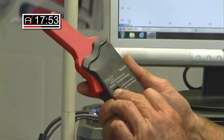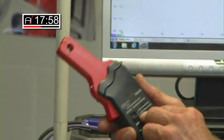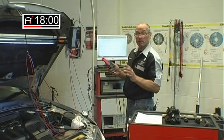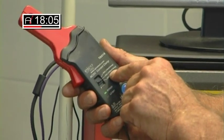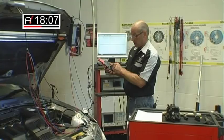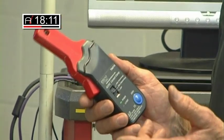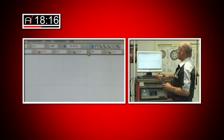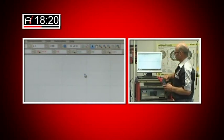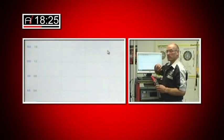We turn the Hall effect inductive clamp on to a 20 amp range. These injectors will use about 18 amps of current, so a 20 amp range, and this equates to 100 millivolts per amp, which means if I set 10 amps per volt, so if I set a 2 volt range, that gives me a 20 amp span, which is what I want, and the conversion is straightforward. 4 amps, 8 amps, 12, 16, 20 amps.